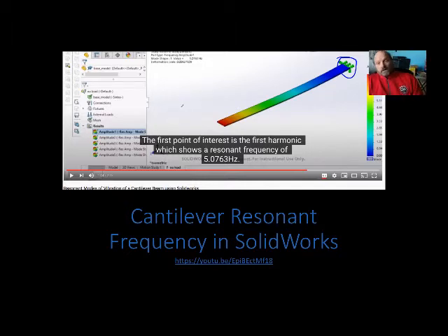And I have a kit that I put together for technicians and engineers to learn about cantilevers and do the experiment in the classroom. You can measure the resonant frequency using a video from your phone, and then you plot the resonance as a function of length, as a function of width, and a function of thickness. And then you add some mass to the end of it, and then you can turn it into a scale, and it works out really nice.